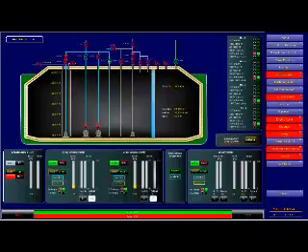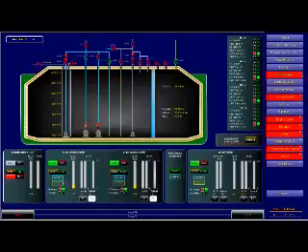Let's do it for an experiment, because we have got another pump to start. So let's do it. Put on standby, which is this pump. Okay, standby. Okay, and just slow start it. You will see how the revs will go high.